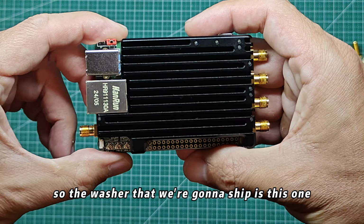So you have your USB Type C, you have your USB OTG cables, and then there's an SD card slot over here that you can boot the firmware from. There's a boot options pin over here, so pins 2 and 3 are to boot from the flash, and 3 and 4 are to boot from the JTAG. So yeah, this is pretty much how the device looks like.